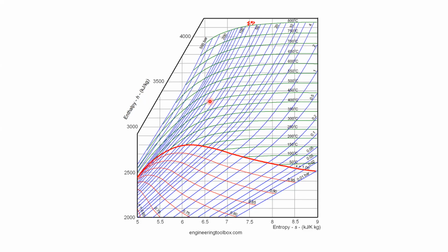At this position, I have the H1 value at 450 degrees centigrade and 70 bar. This is the 450 degrees centigrade line, and this is the position where I got the first point. At 450 degrees centigrade and 70 bar, I have the first position. If you take the enthalpy values on the vertical axis, it may hit at this position.